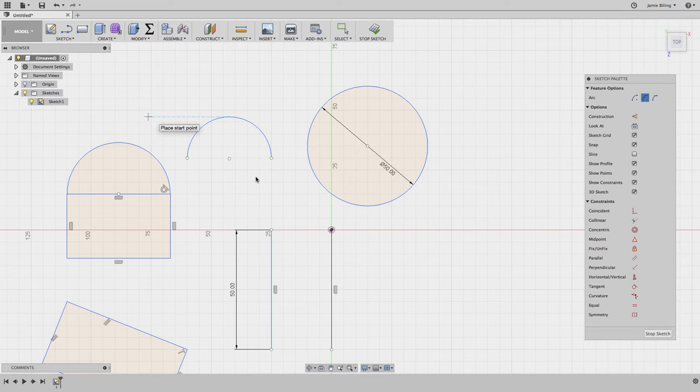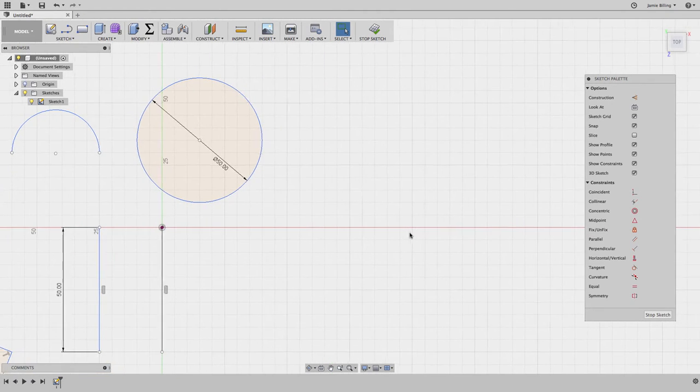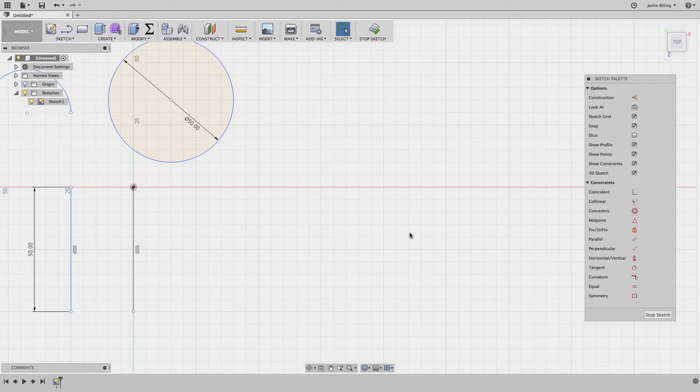We can also create arcs while sketching lines without having to stop our sketch and change tools. If we find some space on the canvas, then select L on the keyboard to activate the Line tool, we can sketch lines in succession, but also we can sketch arcs without having to change our tool. To sketch an arc whilst using the line tool, click and hold the left mouse button at the point in which you wish to begin the arc, and with the left button held down, simply sketch out the arc using an arc-like motion with your mouse.